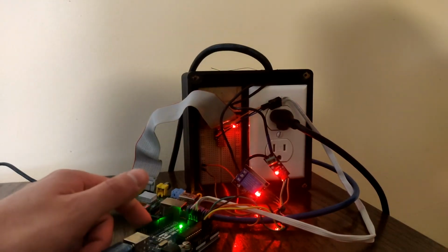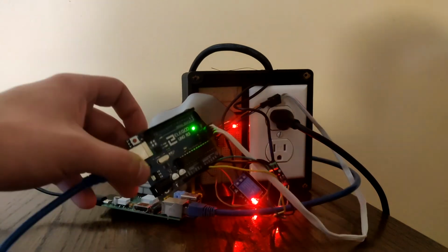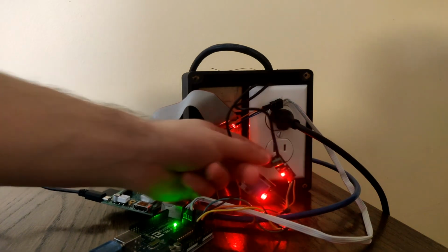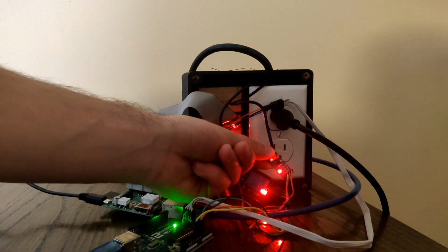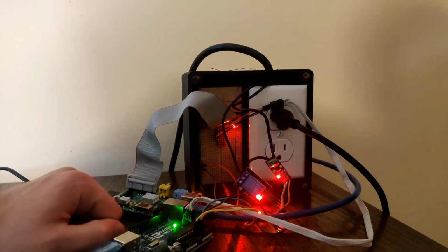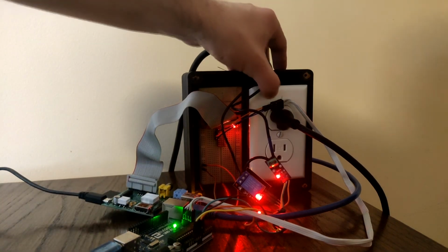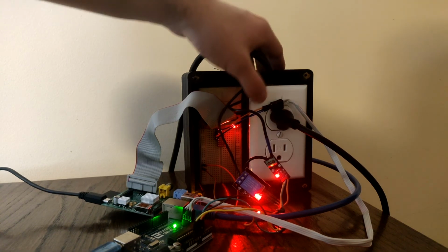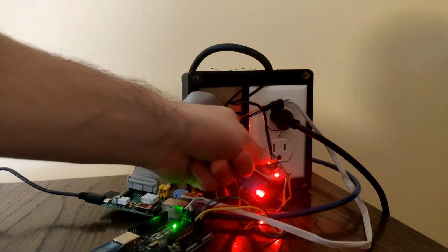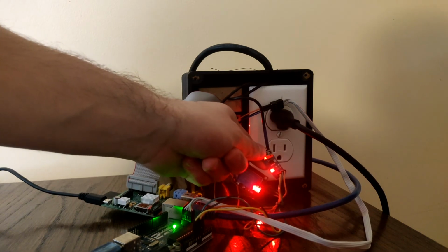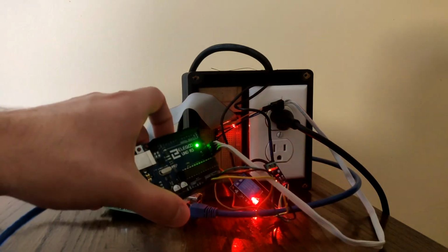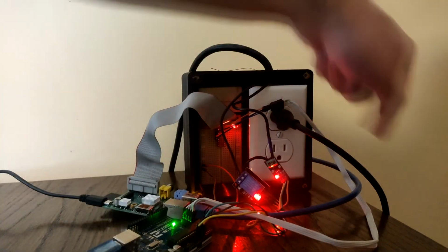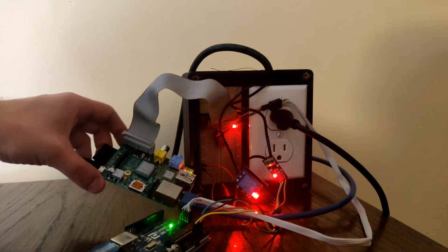Our smart outlet is comprised of several main components. We have an Arduino Uno, we have a Raspberry Pi, we have a 5-volt relay along with the ACS712 current sensor. The way our outlet operates is we plug in a device here to the plug itself, and then the current that the device draws goes through this wire through our current sensor, which outputs an analog value between 0 and 5 volts. Our Arduino reads that value, converts it to digital, and then sends it over the SPI interface over to our Raspberry Pi.